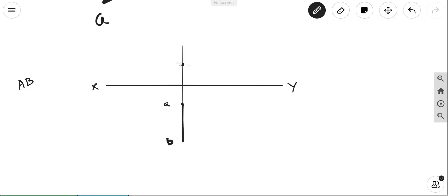So what point will be obtained here? We will get the front view of point B, so we have B dash. We will get the front view of point A, because it is behind this point B dash. So in the bracket, after a comma, you can mark it as A dash. We will also have the vertical trace behind A dash. So again, we will further mark this as the vertical trace also.